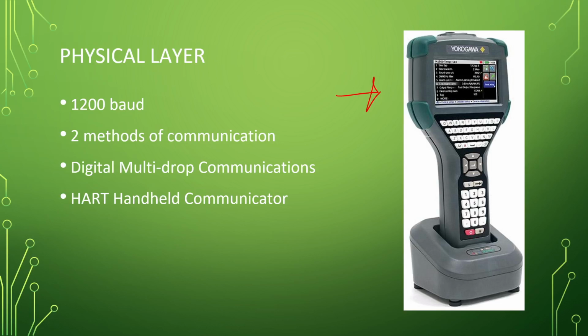This can read that information, it can write information, it can have a range, it can be used for calibration. Yeah, it's great. And as I said, this can be connected anywhere in the bus as long as the loop impedance is at least 230 ohms. So that is something that you need to think about, but it's really not the biggest problem in the world.